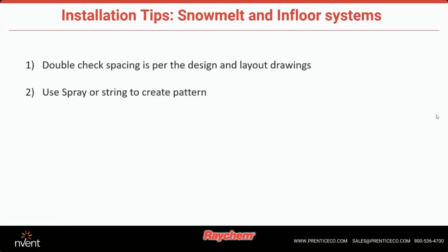I do highly recommend, instead of trying to lay out the cable right away, if you want to use a spray can or even a string and try to create that pattern, that just helps the guys to have a pattern for them to mark and go and efficiently install that cable, so that at the end of it, you don't figure out that you've got an extra 50 foot and you don't know what to do with it, or you may be short 20 feet and now you don't know what to do. Sometimes creating that pattern ahead of time will allow for that not to happen.